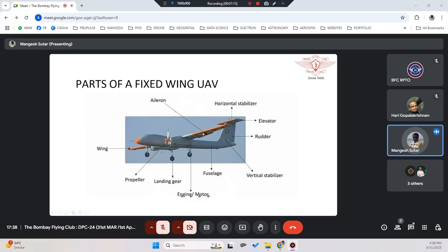So depending upon how the drone has been designed, basically they may have designed it with respect to the CG. Maybe they wanted to keep the tail up and down, or whatever other way they want to keep the control of the fixed wing. So you have a horizontal stabilizer on the top with elevator attached. So what moment will we have if I move the elevator?